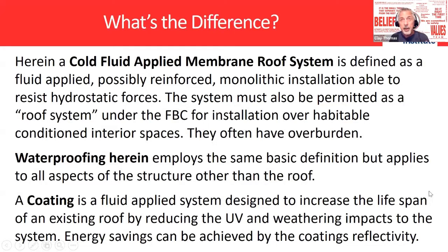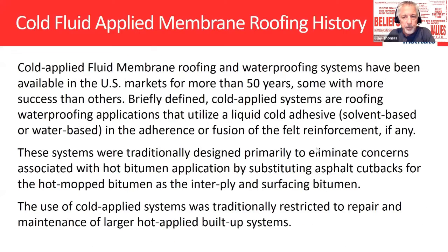Also, we talked about increasing the SRI for a roof system, the SRI being a component of the reflectance of the roof system to reduce heating and cooling costs in the building. So a byproduct of having a white roof in Florida is reducing your cooling costs due to the reduction in the heat load. Cold applied membrane systems have been in the market for over 50 years, some with a lot more success than the others.